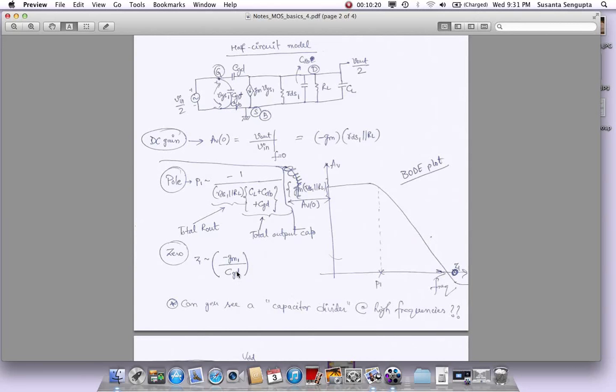We'll see that again. So we calculated a pole, and hopefully now you understand that when you have multiple paths, it will also form zeros, and you can simply, in a very qualitative way, calculate it without solving the whole expression. If you did the whole derivation, you will get the same 0 there too.